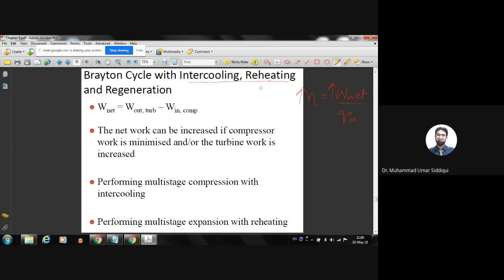In the same way, it happens in the case of the turbine as well. The turbine has to reduce the pressure so the expansion process can take place inside the turbine. But when the pressure is being reduced, at the same time the temperature of the gas is also being reduced inside the turbine. And when the temperature is reduced, the gas starts contracting. When you reduce the pressure of a contracting gas, less work output is going to be produced from that.